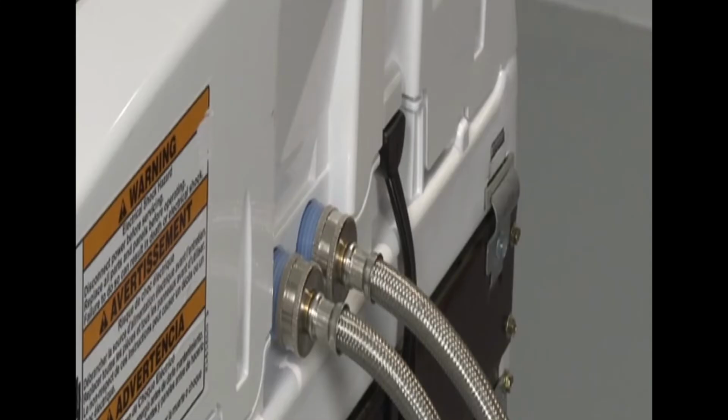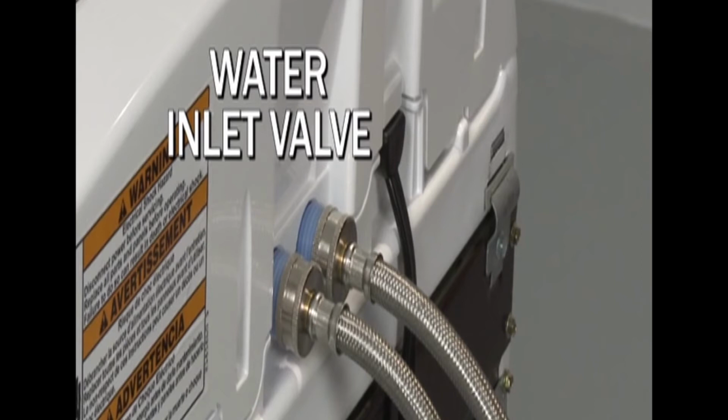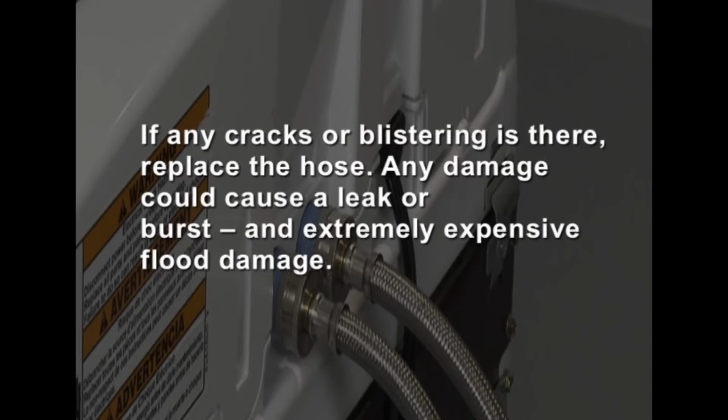Check the washing machine's water hoses for signs of wear or weakness a few times each year. If there are any cracks or blistering, replace the hose. Any damage could cause a leak or burst and extremely expensive flood damage. Most manufacturers recommend replacing the hoses every 5 years. For more peace of mind, use high quality stainless steel hoses.